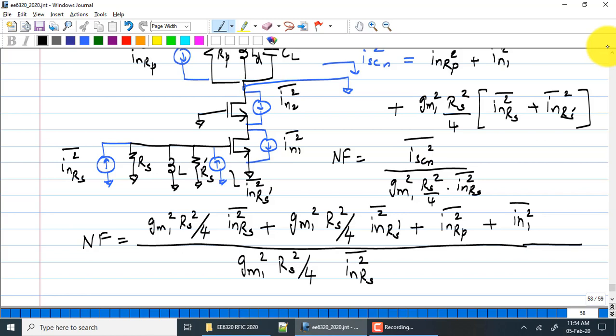But actually it doesn't matter, because assume that you didn't add resistance, the transistor itself had some parasitic resistance at the gate. Even if you match that through a matching network, it will produce the same amount of noise as a physical resistance of 50 ohms. I hope you understand what I'm saying.